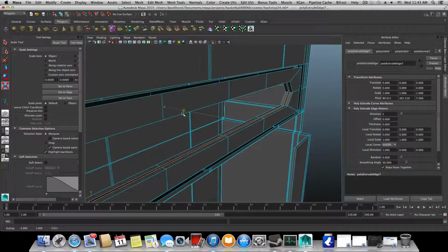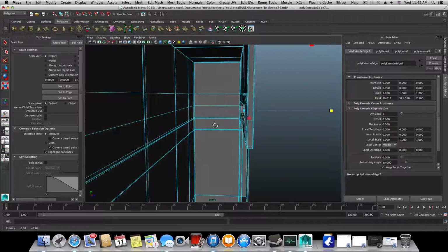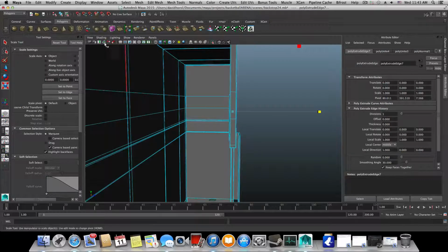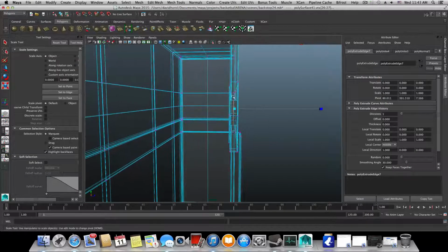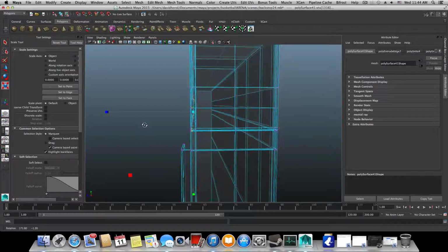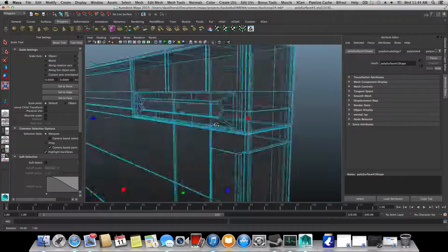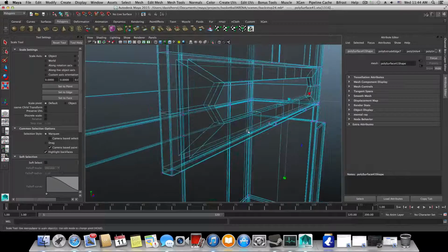And you see the cube that I'm holding? I want to make sure that it meets there, that way. This way I can come and take a look from the side that way, turn on X-ray, right click, choose vertices, and I can grab all the inner vertices there at the same time that way. Well, it's a little bit weird to look at this that way, but that's fine. You can do this, okay? See, I already picked them all in one grab, so that's good.